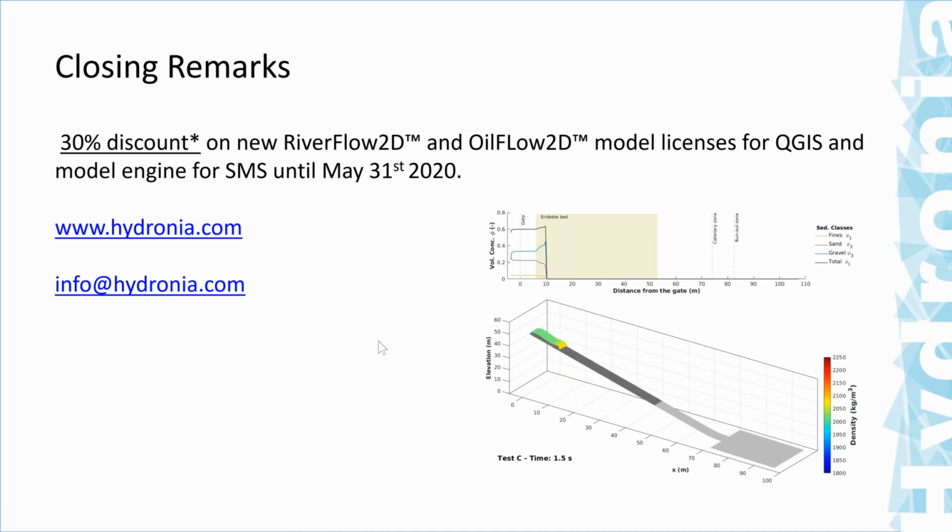I have here a question: if you have to construct the cross section of the channel? The topography is based on a raster DEM or any other form of digital elevation model, but you don't essentially need to have cross sections in the model. You extract the cross sections for the results.